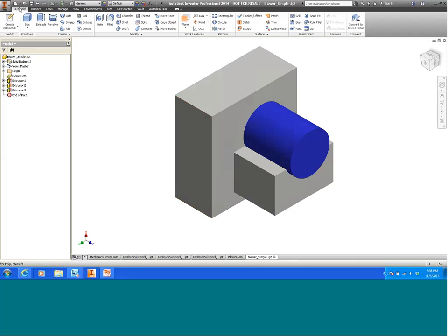What's really nice here is that this is all geometry, and I can go in and actually even add features to it. So I could go in and add a chamfer to this area to actually refine and define the space claim even just a little bit better. And then I have this model that I can save and send to anybody. Before I just go on, I just wanted to highlight that if you look over in the model browser, each of those envelopes were generated as an extrusion. So you can see extrusion 1, extrusion 2, and extrusion 3. And that's the reason why I was adding the chamfer to that extrusion 1. Okay, and then I mentioned that I created it as a single body, so you can see it's all one single body.